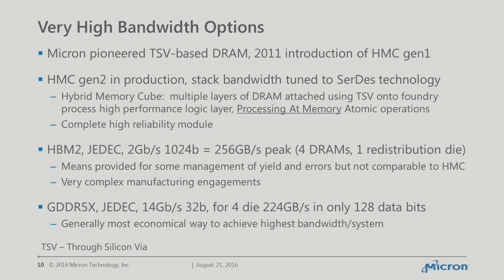It's an extremely tuned device. The whole point of the internal architecture was, if we're going 3D, what should change internally in the DRAM? And so we actually did that. We made the DRAM units really small, and then instead of only a few, or traditionally one, we went to 16 internal channels. The whole point was reducing data movement, right? Your data has to go a tiny little bit in X, a tiny little bit in Y, a tiny little bit in Z, and then you've got the data going to where you want it.